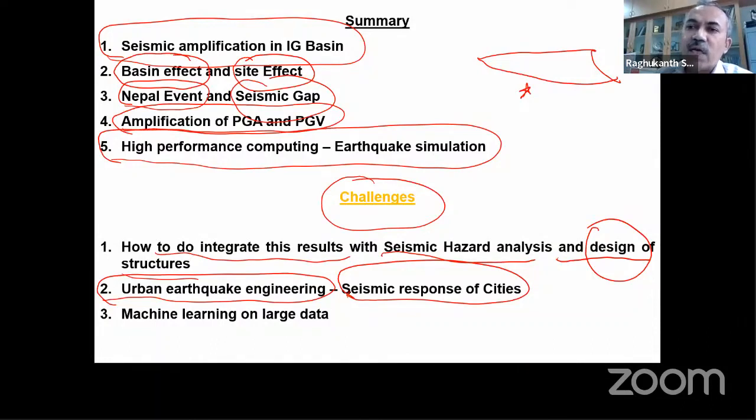But the element size has to be very, very small. Right now, in the simulations I have shown you, the element size is 0.8 kilometer or something, but when you are trying to work at a city level, you have to come to meter level basically. So this is also a very, very important area which one can explore through this type of computational model.